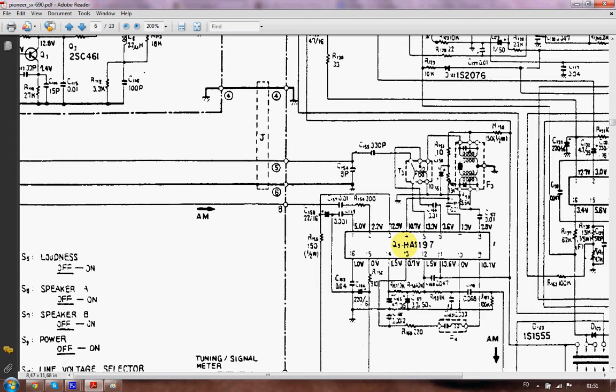And if you find that and compare that internal schematic for this chip to this case and see where you have the voltages in relation to ground, as I told you a moment ago, and see where you lack the voltages. And if it seems like you lack voltages on the chip's output and the voltages are okay on the chip's input, chances are great that the chip has failed, if you know what I mean.